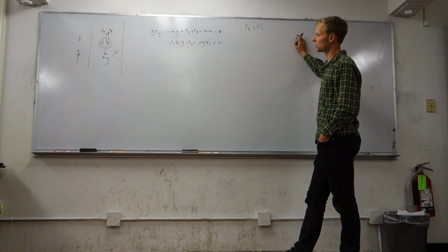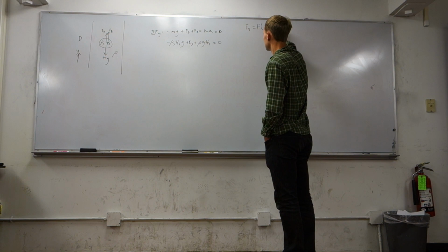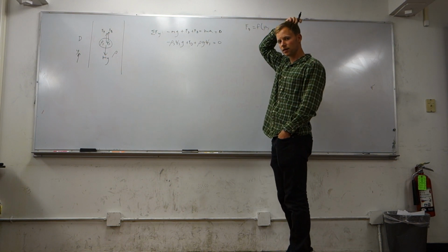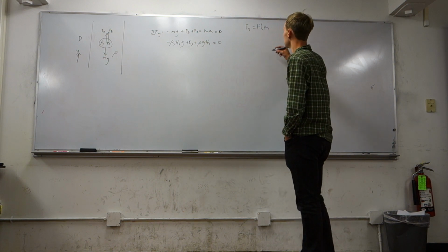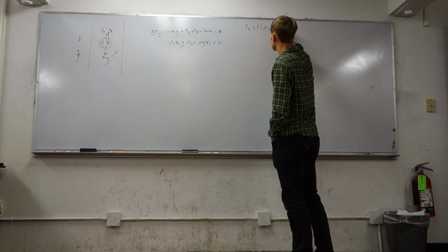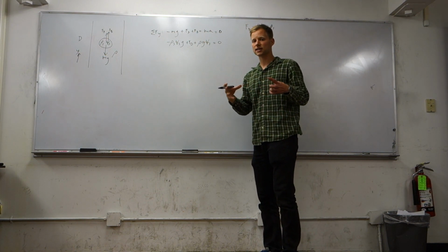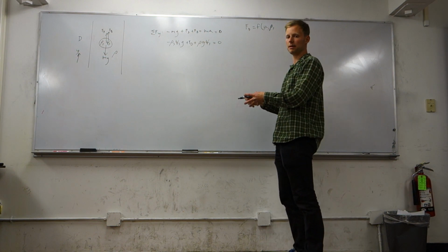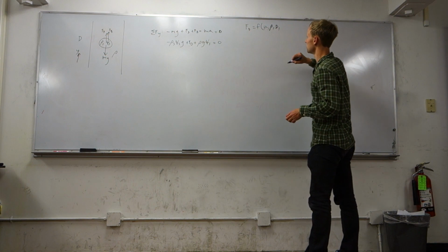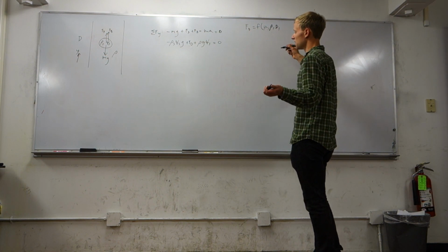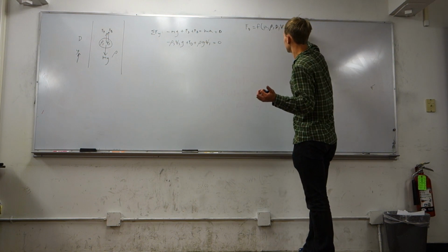So the physical parameters here, which we think might be important, are going to be the viscosity of the fluid, because if you think of this as dropping a sphere through honey versus air, you're going to have different drag force. The density of the fluid might matter. Some characteristic length, some size of our object in the fluid will matter. A BB and a bowling ball have different drag forces on them. So let's call that the D, the diameter of the sphere. And then the velocity of the moving fluid will probably matter. So that'll be a V.